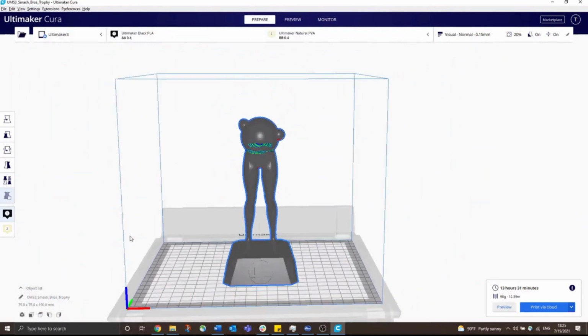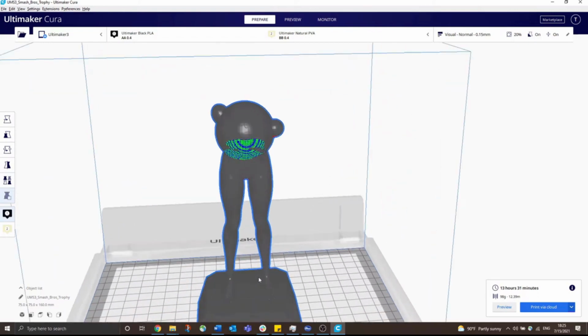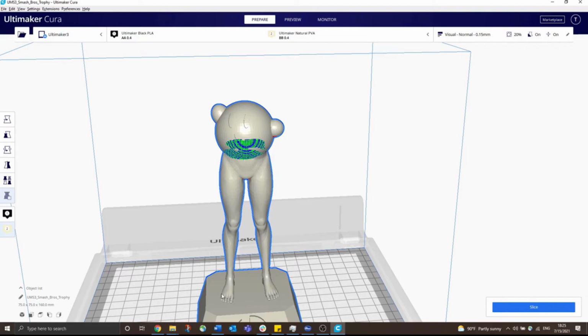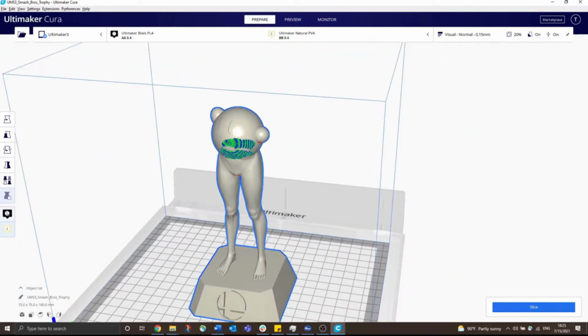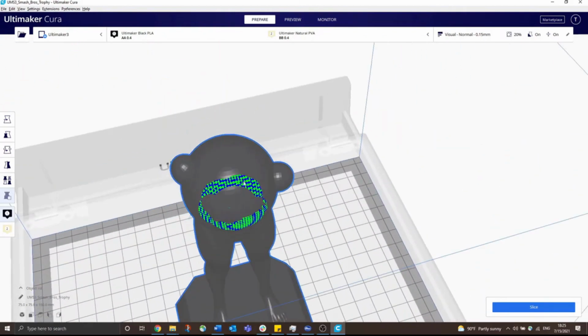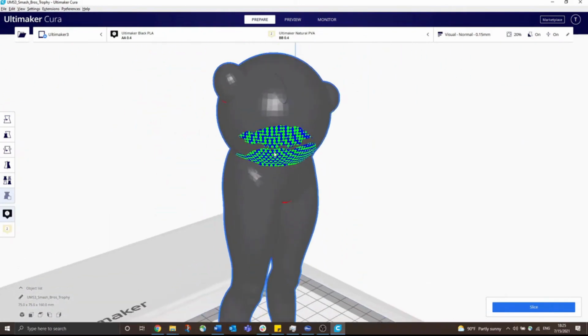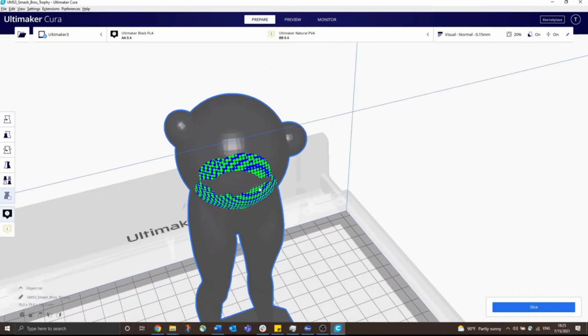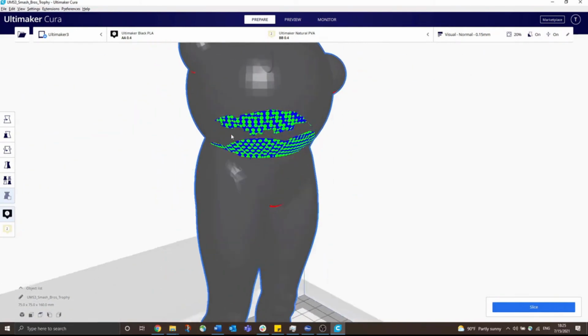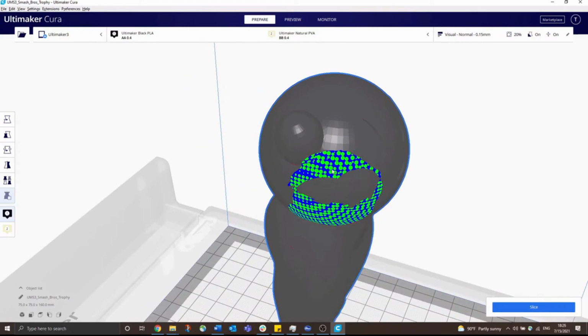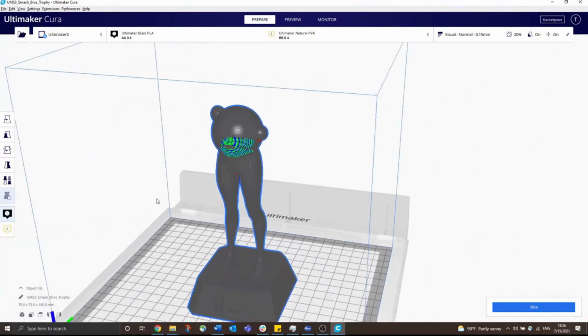Okay, and then like I specified, on the left, the bottom two buttons specify what model material you want to use. So if I select 2, this thing is going to be printed in PVA, which is the water-soluble material. The green highlighted region you see here is an issue with the file. Since mesh files are based off of surfaces, you get this when you overlap surfaces. I recommend not printing parts with these surface issues, since worst case they break the printer.